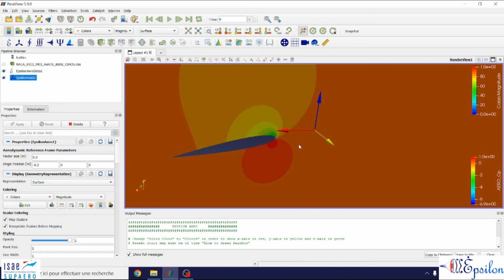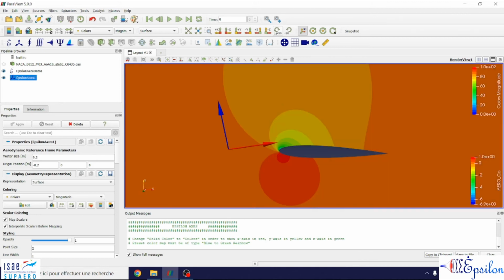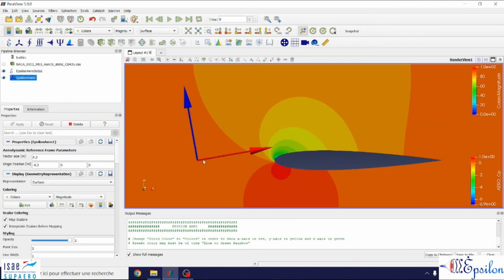As you can see, this 2D case has been prepared with an angle of attack of 10 degrees, and this is actually the angle between the, let's put that, it will be easier to see, the angle between the aerodynamic x-axis and the mesh x-axis is exactly 10 degrees. And it actually generates the aerodynamic reference system automatically because it reads this information.